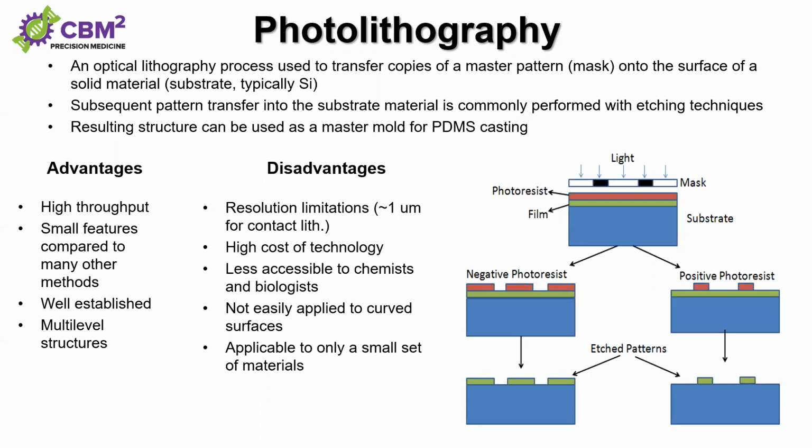We can produce, as I mentioned before, very small structures, but the practical resolution limit is around 1 micrometer using the conventional photolithography method. Some disadvantages: the resolution is limited by the use of light and equipment, and the equipment cost is pretty high.